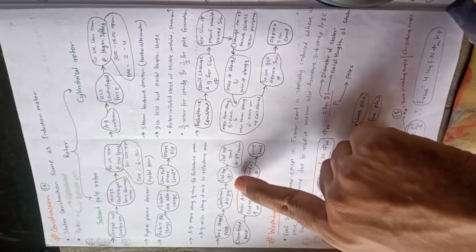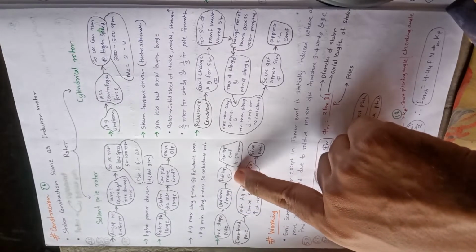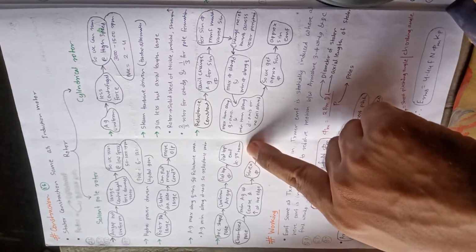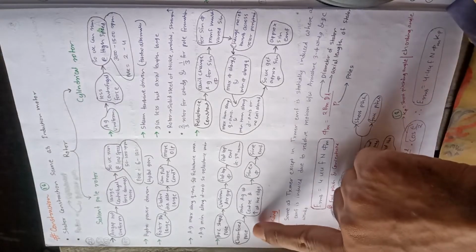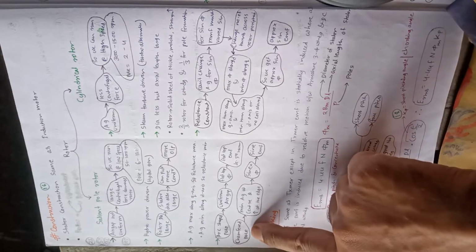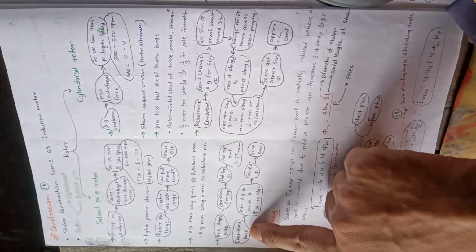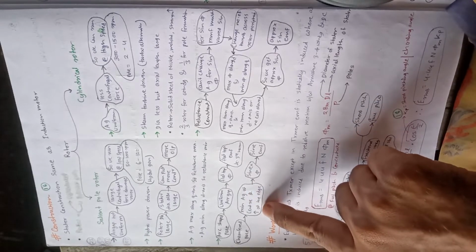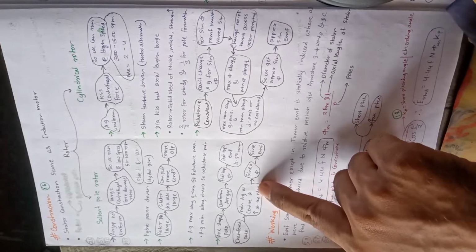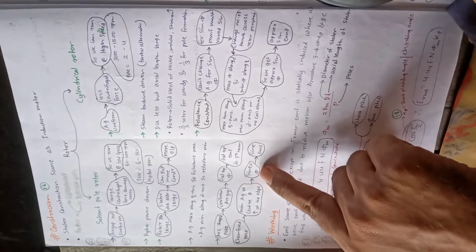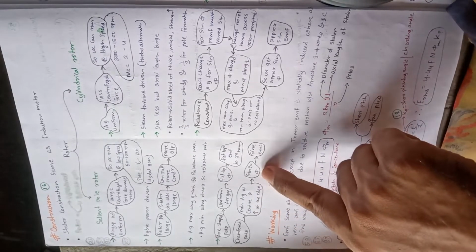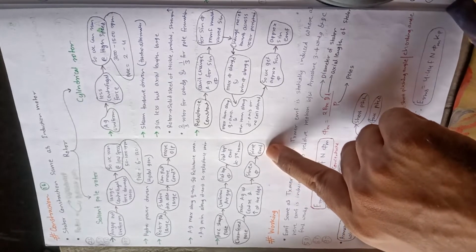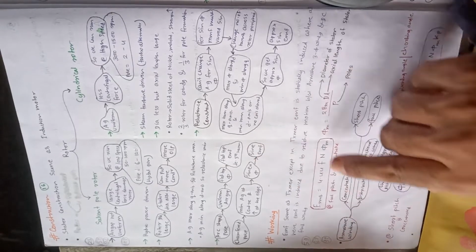So in arc shape pole, the air gap is uniform. We saw flat top flux is formed, and due to flat top flux, flat top EMF. Flat top EMF means third harmonic is present, so we use a chamfered pole. In this, minimum air gap is at the center and the air gap increases at the edge. In this way we get sinusoidal flux, and if the flux is sinusoidal, then we get sinusoidal EMF. That is our main motto to obtain.